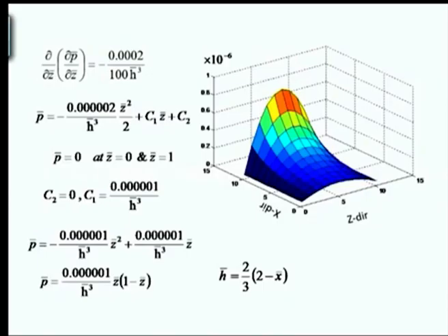We can see the x direction as well as the z direction, we consider the same number of steps, calculating when the value of x bar is 0, 0.1, 0.2, 0.3, obviously the number of nodes is 1, 2 to 11. Similarly, in the z direction also the number of nodes is 11, and based on that we are evaluating the pressure profile.